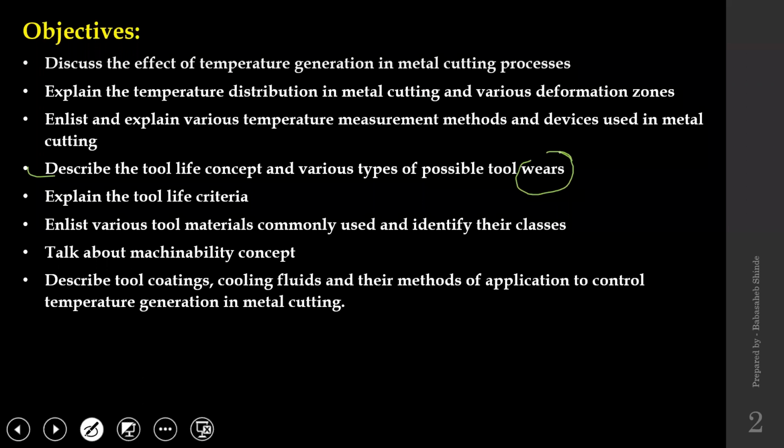And tool life criteria. So once that amount and nature of wear on the cutting tool has been observed, it says that beyond that point we should not use that cutting tool. Either we should regrind the cutting tool, or if you are using an insert, then you should replace the cutting tool, but you should not continue with the same tool, right?